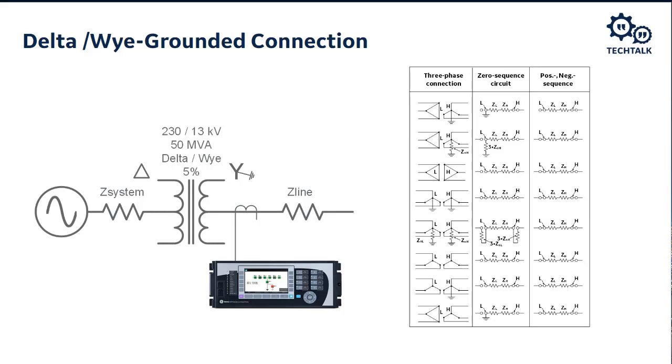Trip the breaker so that the faults don't persist and do additional damage, or impose a public health risk or safety, public safety risk. So that ground there gives us the ability to have ground fault current that we can sense on that relay that we show there.